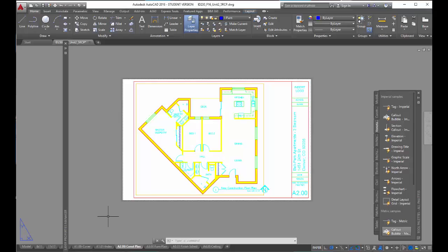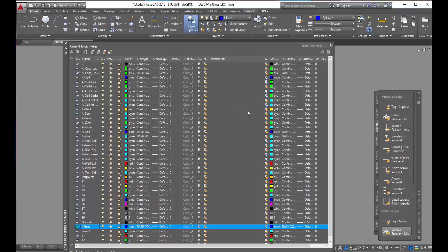As you progress through building the CD set, you're going to see how all of the layers are going to show up in the viewport at first, and then you have to go into each viewport and turn the layers on or off as necessary. So for instance, here I am in the construction viewport, and if I double click inside the viewport, and then I go up here to layer properties, it's actually right here, I'm just going to maximize that. You will notice that I have one set here of layer information, but then all of a sudden I have this other set that was not available to me before. This side is for model space. This side is for that particular viewport.